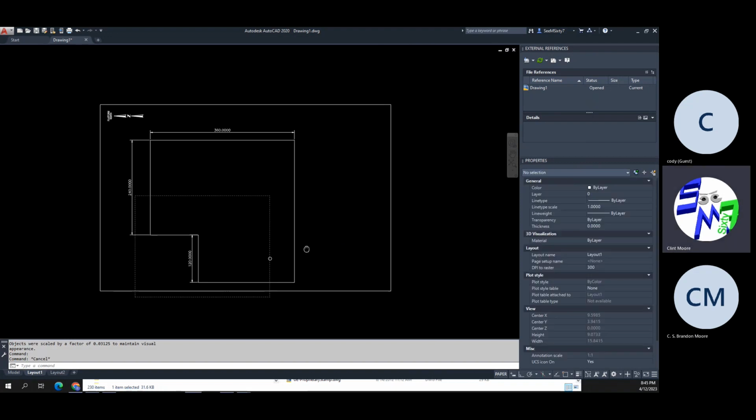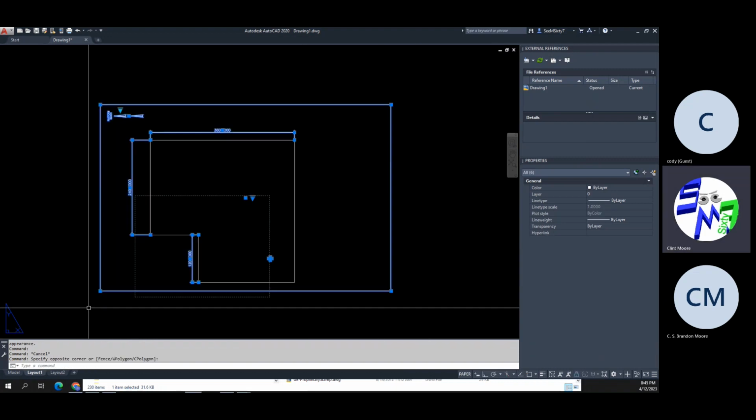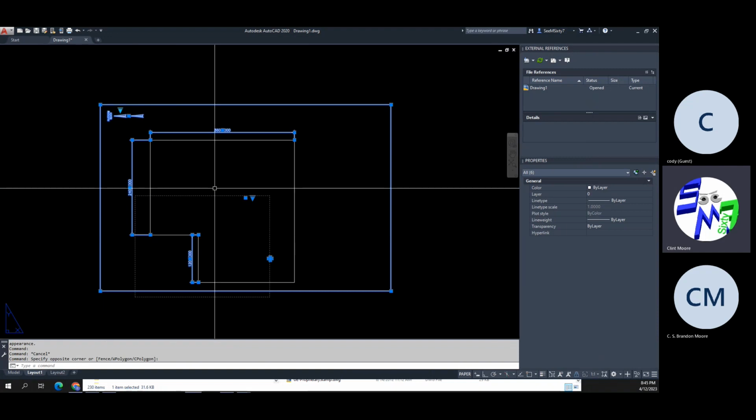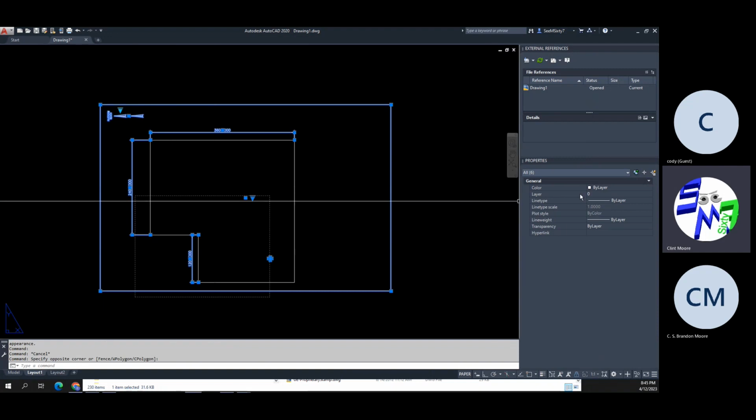Okay, so that's all we have for our drawing segment today. We wanted to concentrate on selection, different types of objects, the methods that you're issuing commands. You have the noun, verb, verb, noun. AutoCAD traditionally started as a verb noun, did not have the noun verb. Okay, and again, I use primarily and dominantly verb noun. Okay, but when I'm using grip edit, the most common thing to do is grab, and then that is actually noun, and then you do something with it, verb.